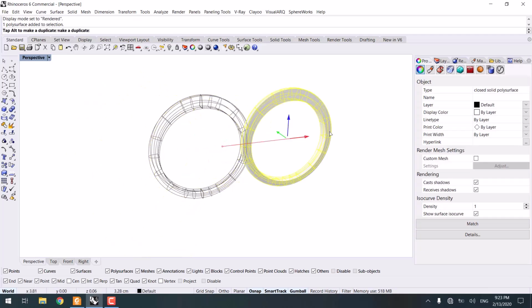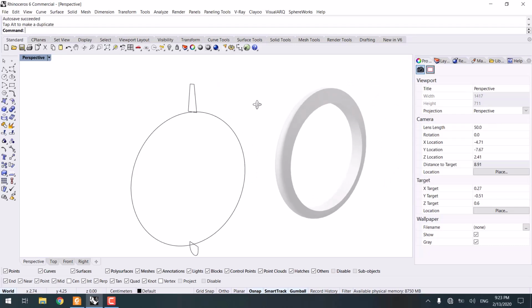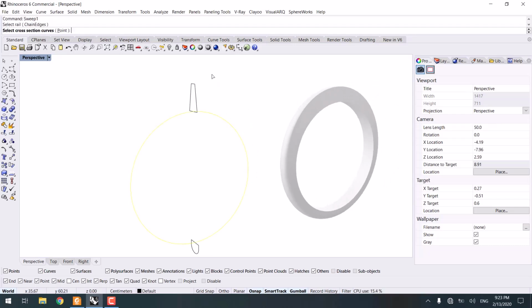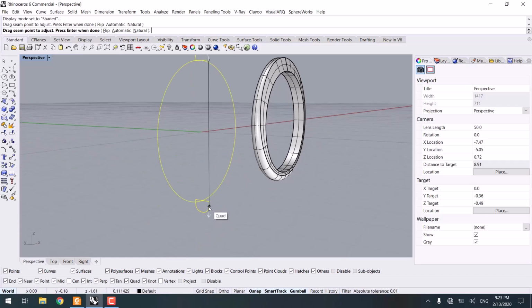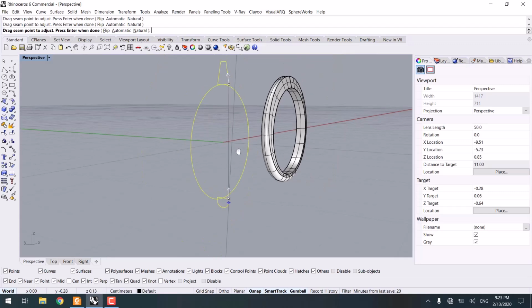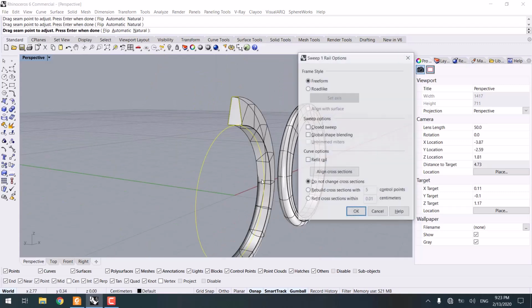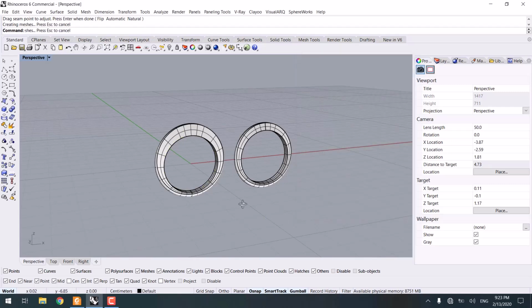Now, to create that deformity that I mentioned before, we can, for example, enlarge the size of this part, the top part here. Then again, we can go through the sweep process. So the path, sections, and specify the arrows. Here we go, close sweep.